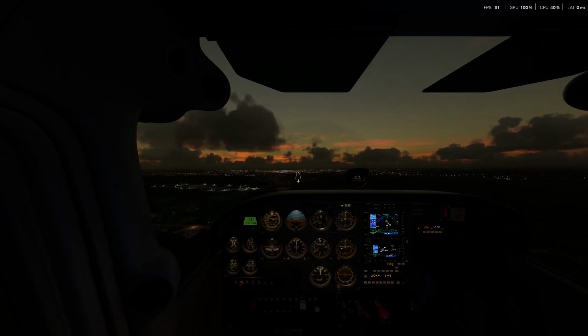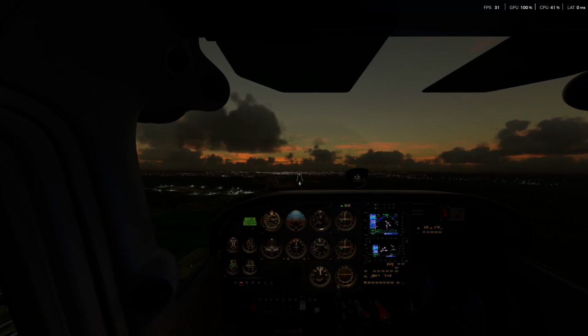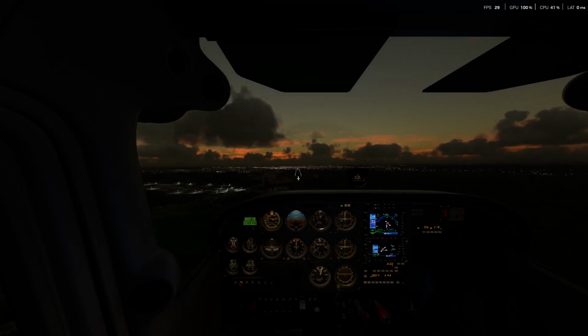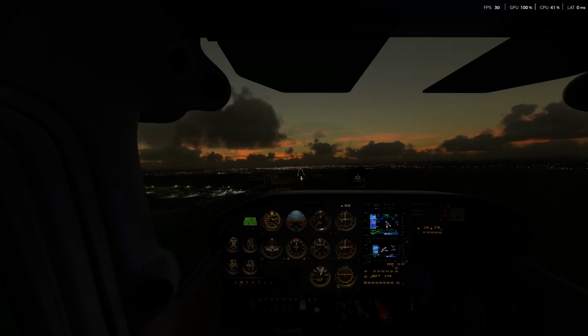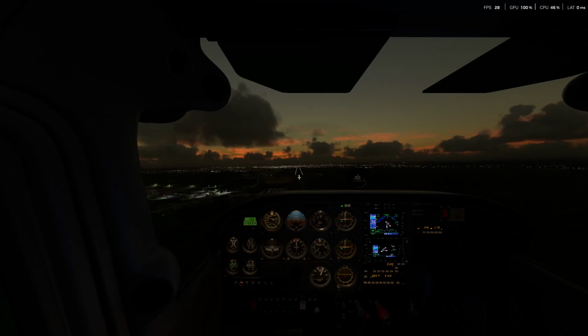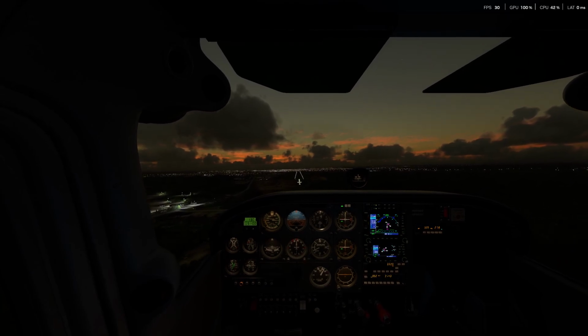So we'll go ahead and go full flaps 30. So under 85, speed check, flaps 30. We're going to lower the attitude there a little bit, increase our RPMs just to account for that increase here. They're getting a little bit low here, so what we'll do is increase the RPMs a little bit more.